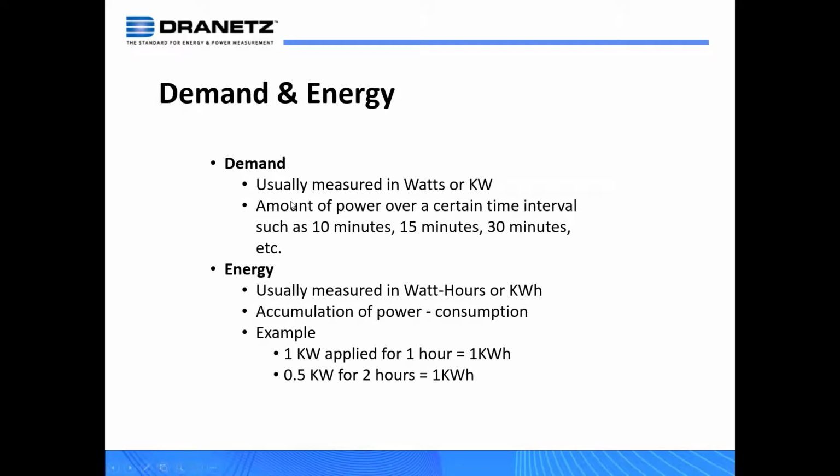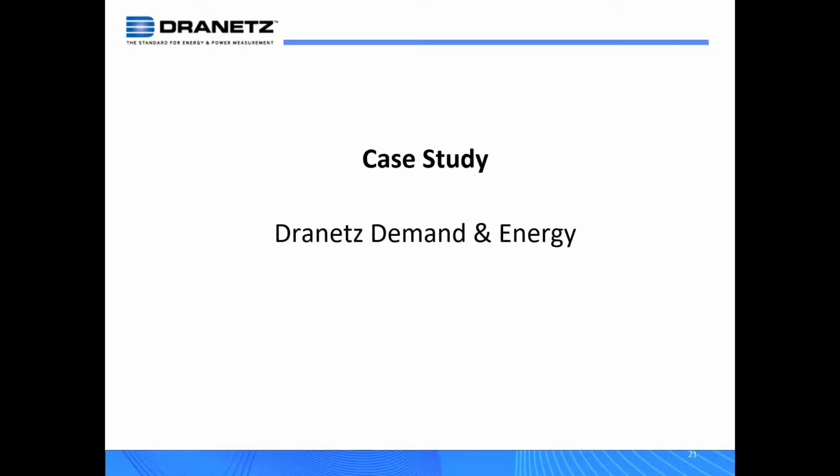Really the difference between these is like, if you use the old water hose analogy, demand is how much water is in the bucket that you fill with the hose, and energy is the rate of water flow, how fast that bucket is filling up. Both are very important to you, and of course to the utilities who are billing us.